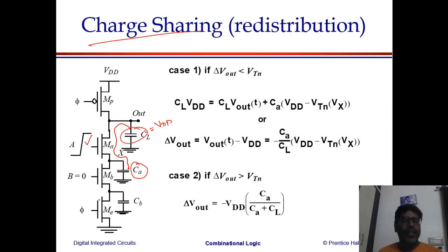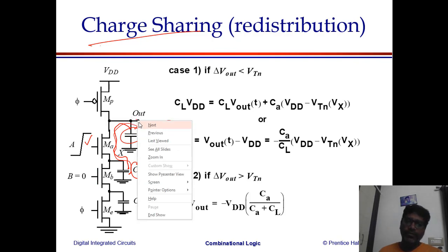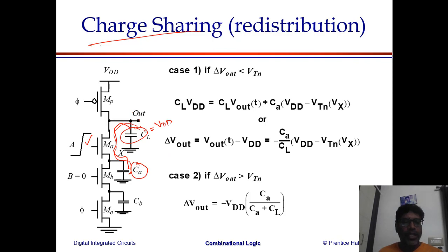Even though the other transistor is switched off, you could see this charge at VDD gets shared with the neighboring capacitance. It is expected to be at VDD, but it won't be at VDD; rather, the charge gets discharged to the nearby capacitor. This is the problem here. This is what you call the charge sharing problem with the nearby capacitance.